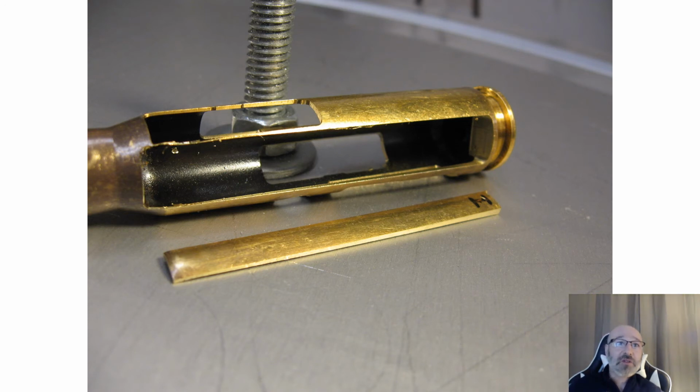So we can see a close up here. We can see we went just as far as we possibly could. And you can even see in this section here how it's a little bit thinner as compared to here. So if we go all the way back, it's extra thick there. So this changed and varied in thickness all the way from the base to the neck of the case right there. Here's your thickness down here at the base, and here's your thickness up here at the neck. And what we want to do is go down through and do micro hardness testing all along this case at these different thicknesses of the case wall.